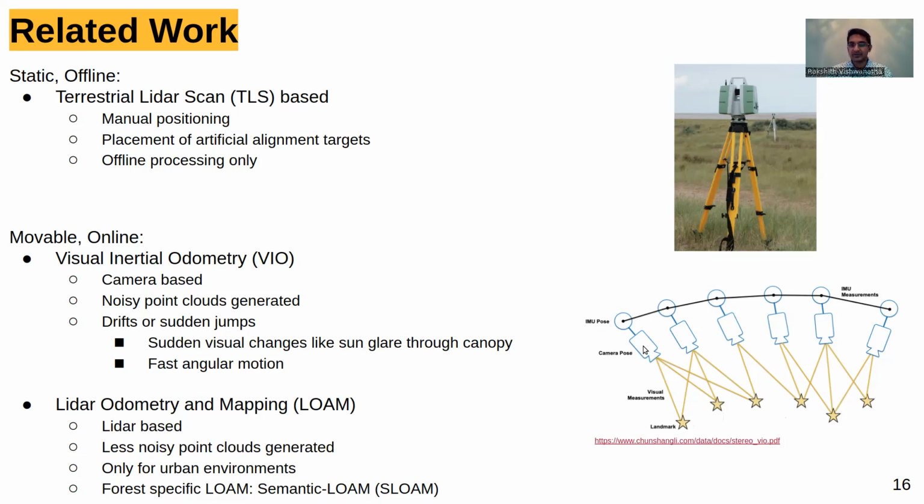Based on the correspondences and stereo geometry, we can estimate how much the camera moves from one point to the other. That is fused with IMU data to get a sense of how much movement there was in the camera, and then also create, if necessary, a point cloud from it.